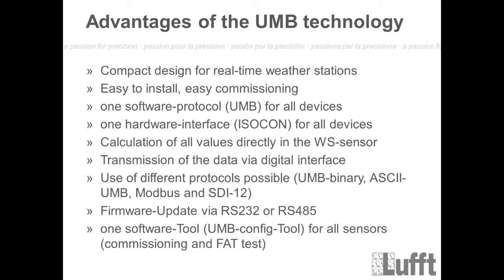After some discussions with our customers, we recognize that the UMB binary protocol, which is the standard protocol of the WS sensors, is not the only very important protocol which the customers normally use. So we have also integrated all the other important protocols which you can configure on the WS if necessary. We have implemented 3 additional protocols, which are ASCII UMB, Modbus, and SDI12.